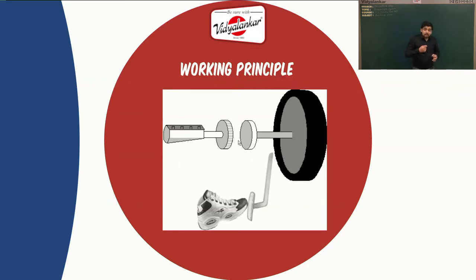Now when we want to disengage this clutch, we provide a force on the clutch pedal. This will disengage the driven plate from the driver plate. When the disc gets disengaged, even though the driver plate is rotating, the driven plate will not rotate. It is similar to a switch in an electrical system. When we switch on, power will be transmitted. When we switch off, it is like a disengage, where power will not be transmitted even though the engine is rotating.